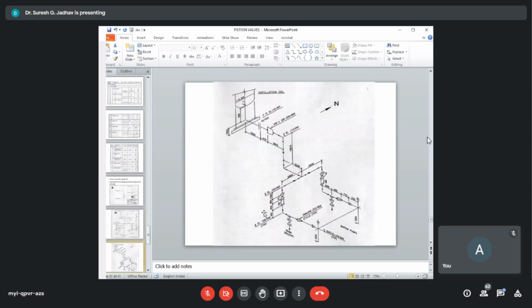See, in the next isometric drawing of piping engineering, here we can mark the different components and different equipment used in piping industries. So here the direction of the north is taken either towards right or left on the top of the drawing sheet. This direction is kept constant in all the areas covered in the plant in actual industry. So is the scale of the drawing. Then, how to start the piping GA?